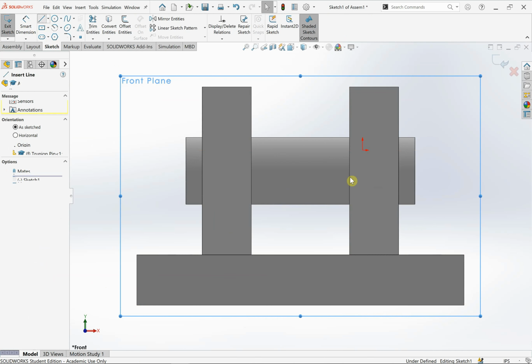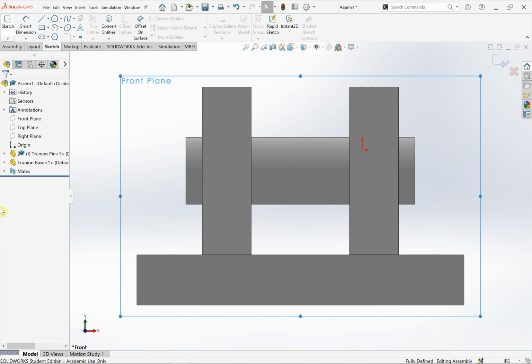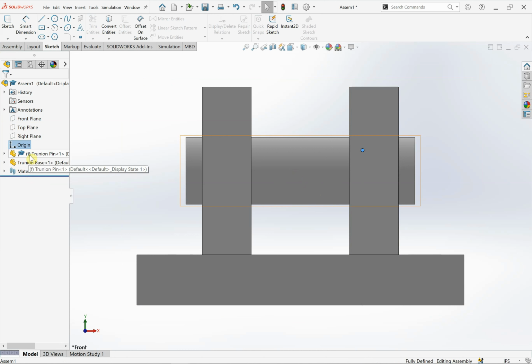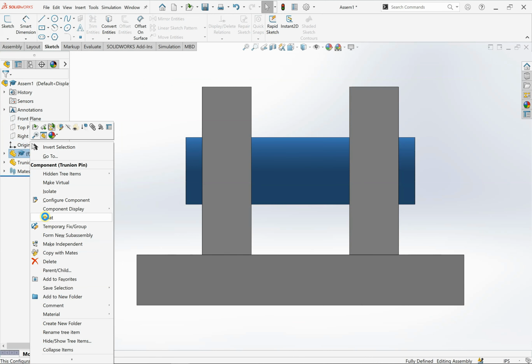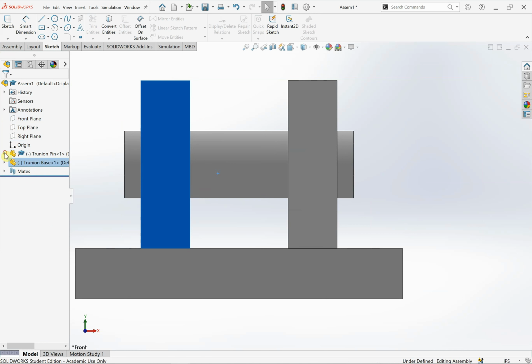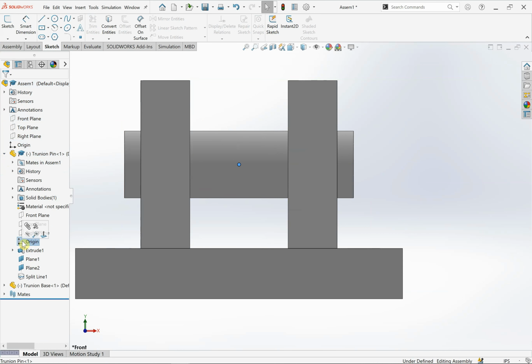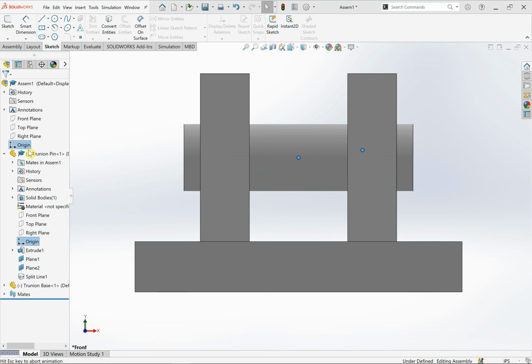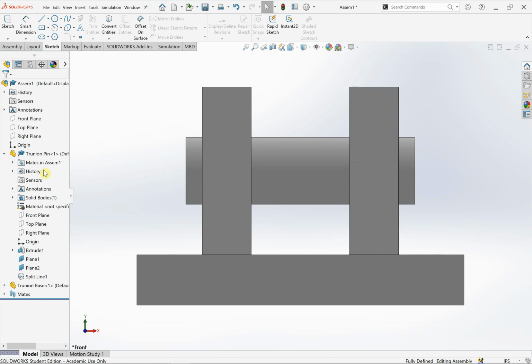And I'm going to draw a line. And you need to be very careful. Hold on, I want to exit the sketch. I want to do one more thing. So if here's my origin, just over here randomly, I'm actually going to float my pin, so now I can just move everything. I'm going to take the origin of the pin and the origin of my assembly and make them coincident